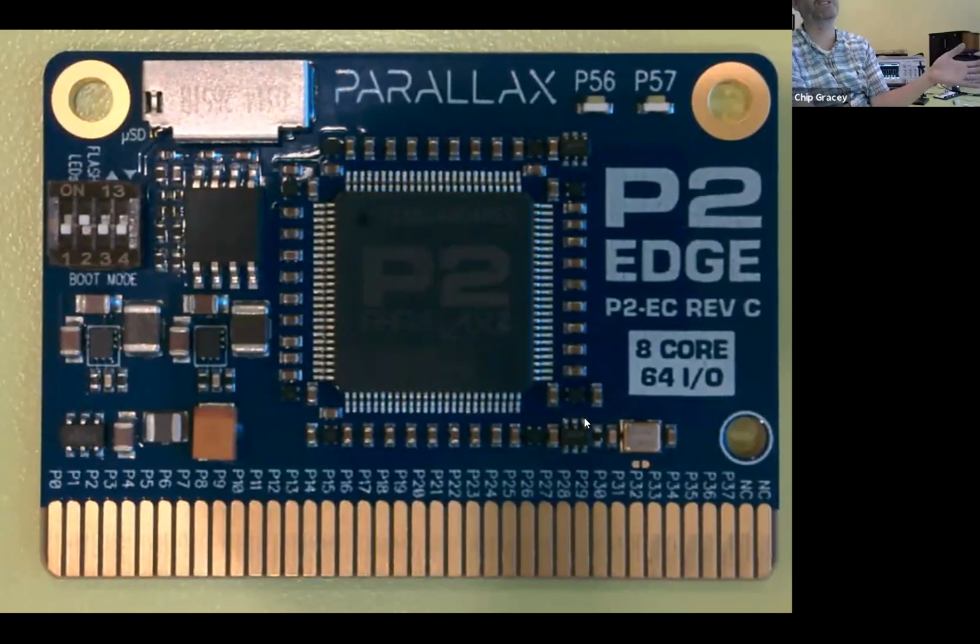So if you have the P2 sleep, it takes very little juice. And this thing is always running. It's always putting a 20 megahertz square wave into the XI pin, no matter what's going on. And as we were talking about, this pin here is not grounded, it's floating. So I made a surgery.